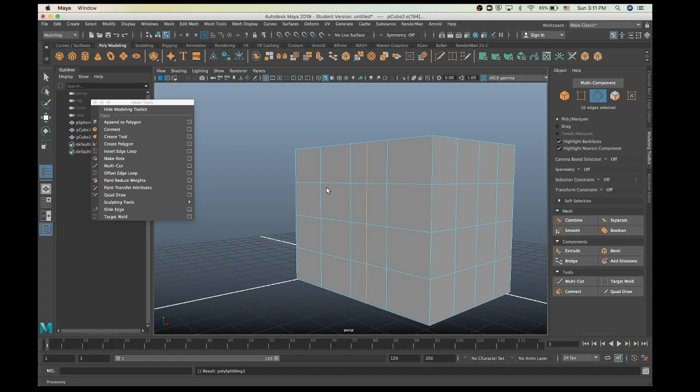And if you hold your mouse, don't release it, then you can basically modify the location of your edge loop. So when I click here, it creates on the opposite side of my edge, and as you can see, I haven't released my mouse yet, and it creates the edge loop, and I can choose where I want to put it. For example, I put it here.